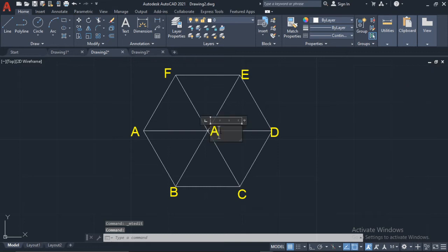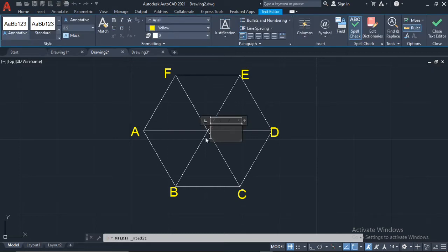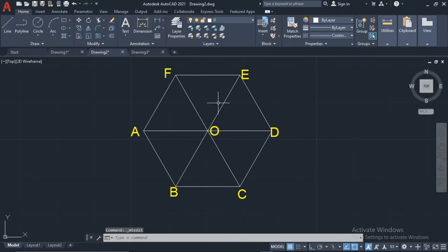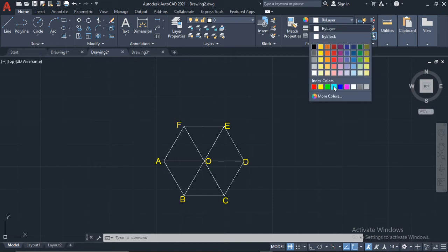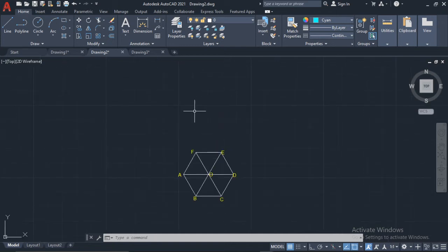Now this drawing is a bit long, but the reason it seems that long is because I'm going through and labeling and everything and explaining. But if you're doing it on your own and you master the technique of drawing the auxiliary views, it won't take that long. So now I'm going to draw an XY line. Now an XY line is a line that separates the different view planes. So this is the plan view, and I'm going to draw the front view over here. So the XY line is going to be between the plan view and the front view. The distance from the XY line to the plan view and the distance from the XY line to the front view doesn't really matter when you're doing auxiliary views like this.